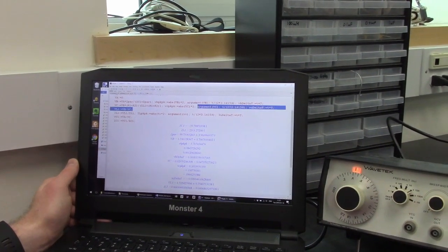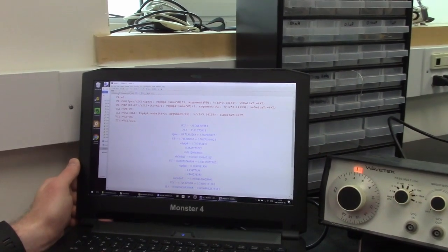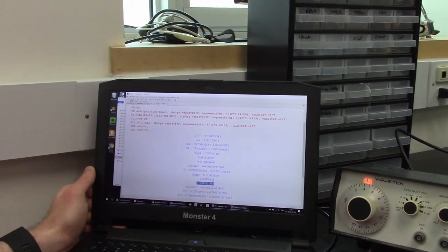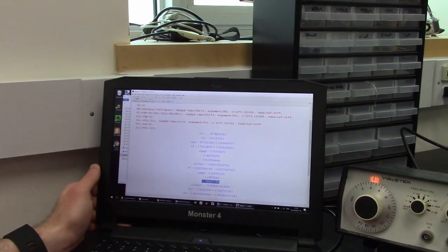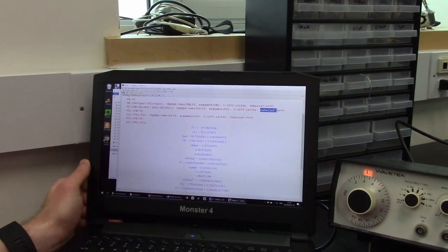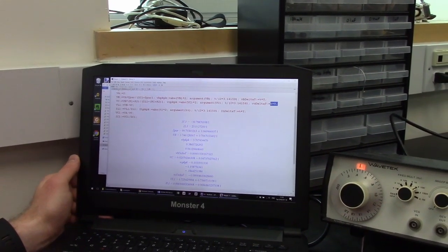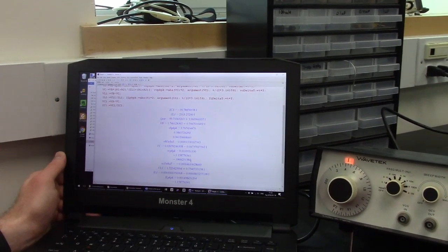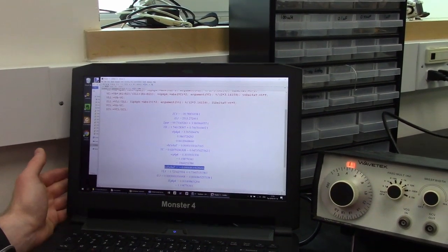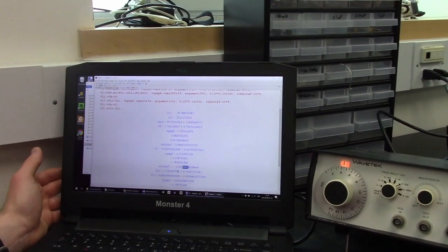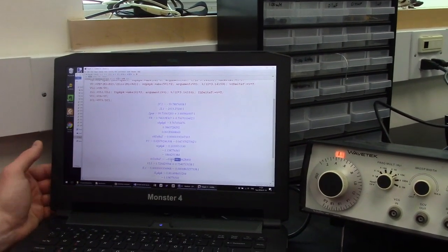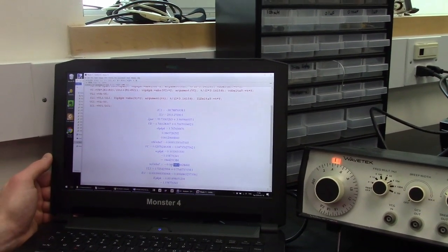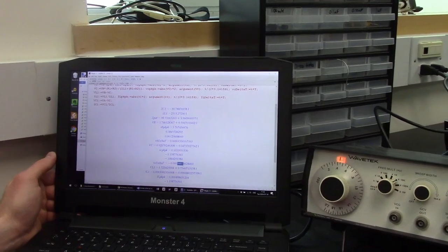So what we'll do is from the argument, we'll now take that divided by 2 pi, and that tells us 0.18, so 18% of a full cycle. And in terms of delta time, we'll take that and multiply it by the period, so 1 over the frequency, and that will convert it into the exact time difference that we should be looking for. So we expect that the voltage at C relative to the voltage at A is delayed by 46 microseconds.